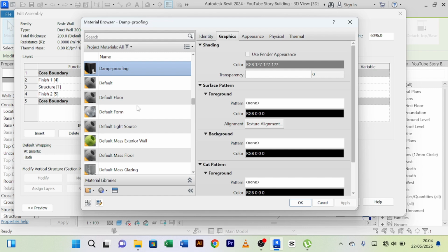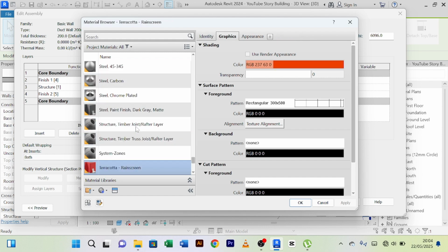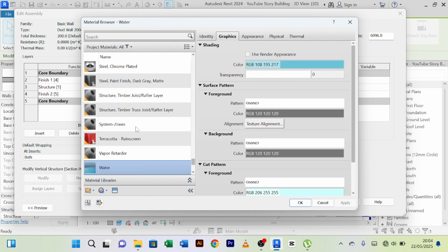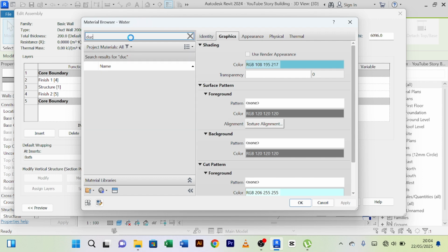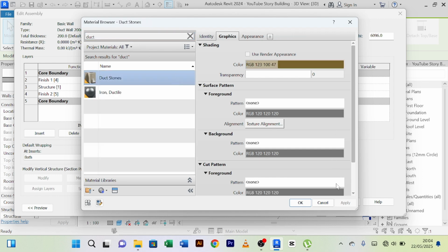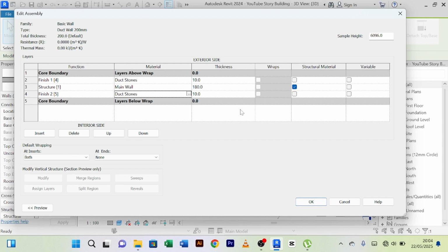So we're just going to now do what? We shall create similar. For you to create similar, you come to this, let me look for it. Here there's match type properties. You click on match type properties, you click on this, you match it with that. You see that? They are now having the same colors.